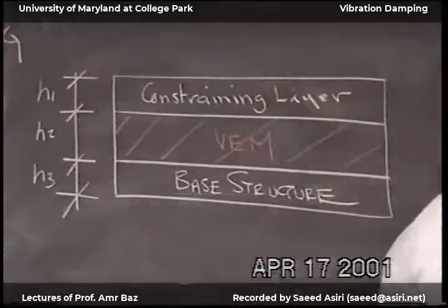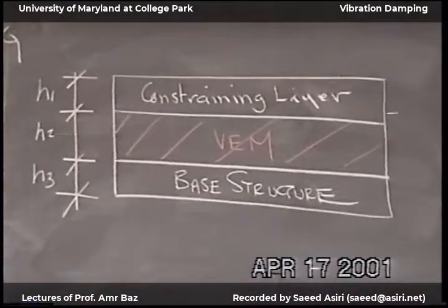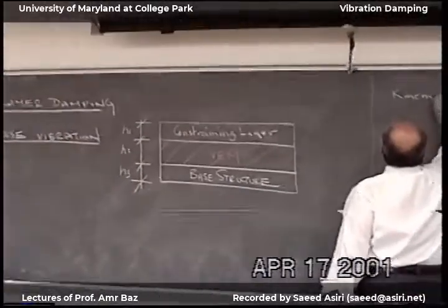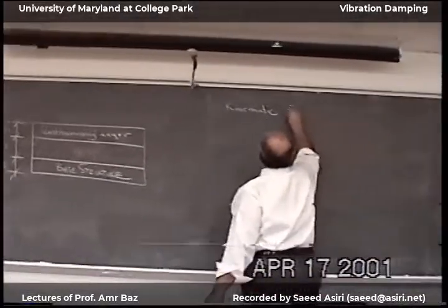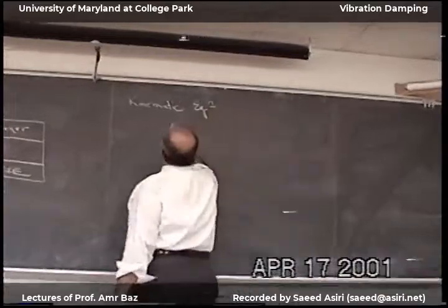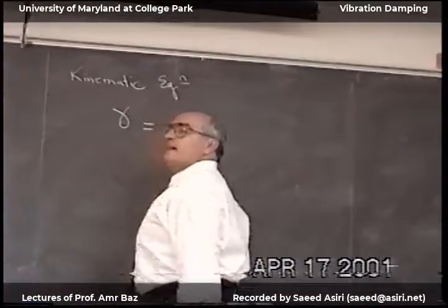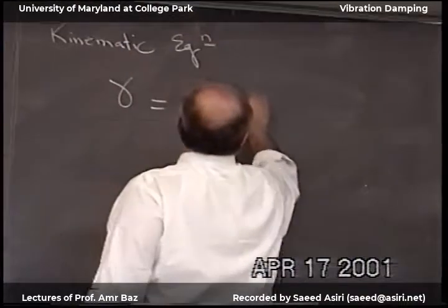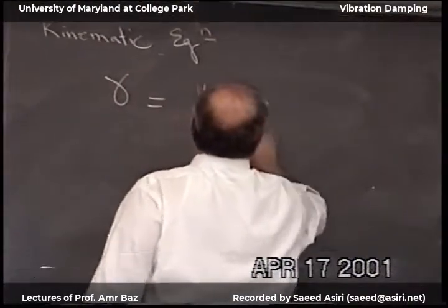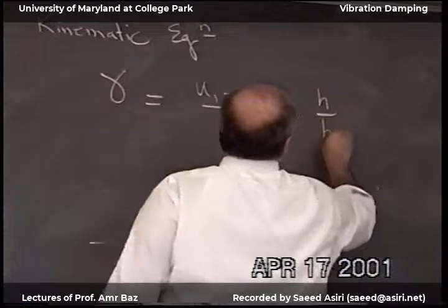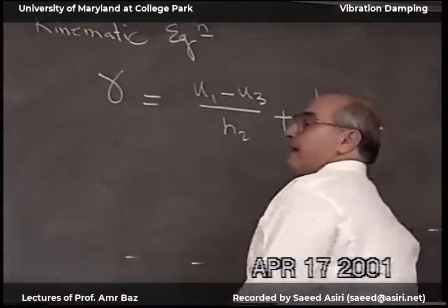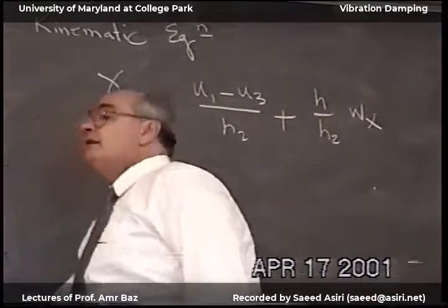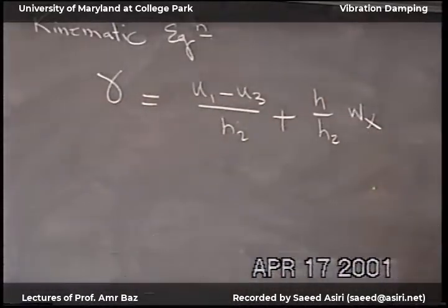And then from the geometry, we found the kinematic equation that relates the shear angle to the longitudinal deflection in the top and bottom layer, as well as the slope of the deflection line.